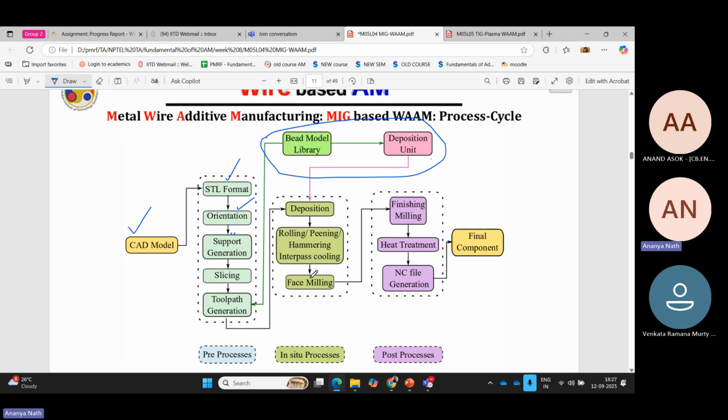Now, this 300 to 400 degrees centigrade is difficult to cool down because of its less heat gradient, right? When you are going to do the milling operation, there will be a continuous flow of argon. That argon will also help as a coolant to cool down the bead. So if it reaches around 150 or 100 degrees centigrade because of the argon, we can start doing the milling operation.